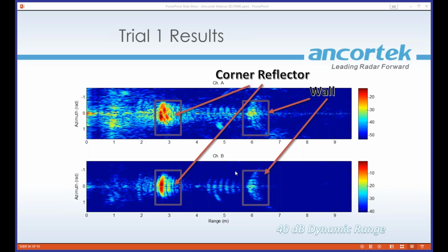Or you can do delay and sum, and delay and sum extracts both the range and the cross range information by essentially lining up the time delay from a pixel with the sample that we received it at, and it looks at all of your collection points, and it sums all that energy up together. So those are the two different ways that we do that. If you want more information on that, again, just email us, and we'd be happy to explain it to you.